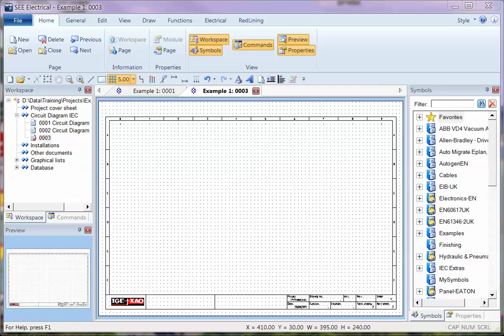I'm now going to show an example of how to set up a more flexible row and column numbering system for the page. So we're going to start by using Control A to select all, right click and explode the page, and then remove these manual numbers that go around the edge of the page.